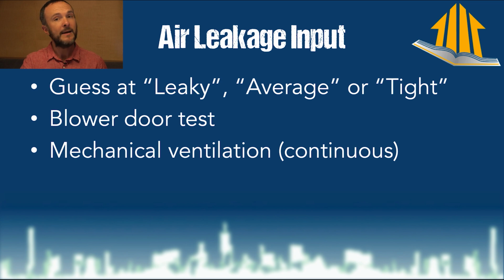And then also you need to put in the mechanical ventilation, which is forced, like intentional, air leakage to outside. And that's generally 24 hours a day. Something that is not just a bath exhaust fan, because every house should have bath exhaust fans, but just turning on the bath exhaust when you take a shower, that does not go into this software.